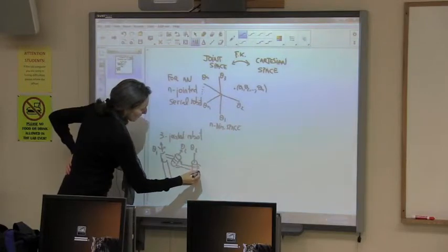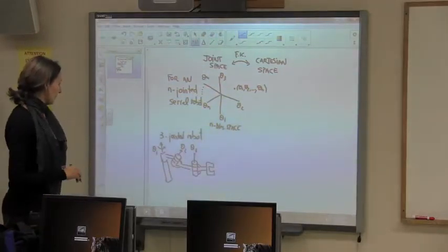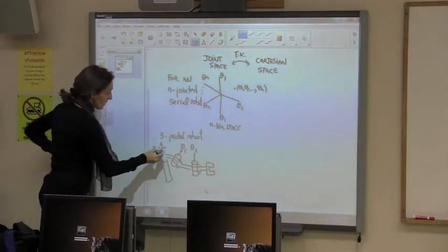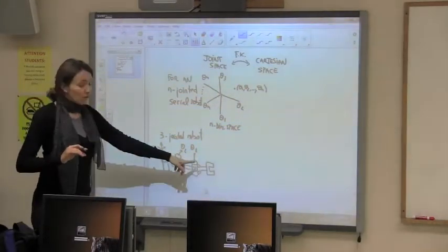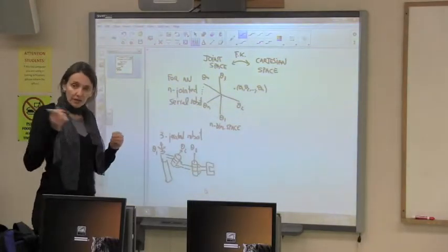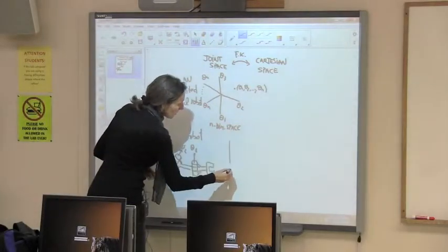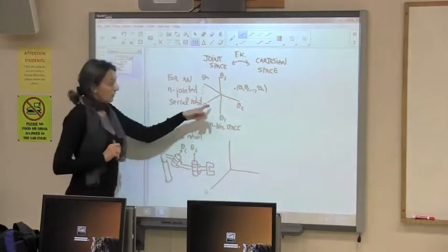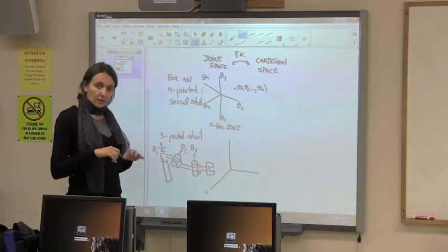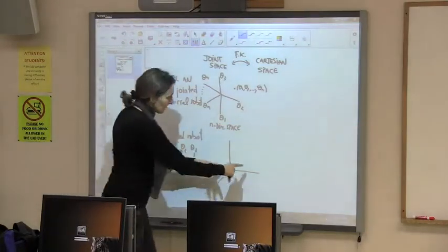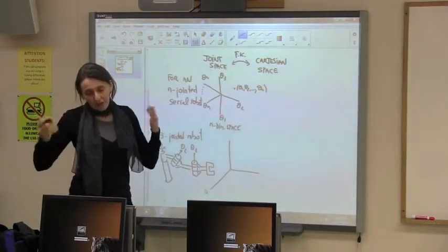So basically in this kind of transformation, everything will be a combination of rotation and translation, right? I'm defining here one with 3 revolute joints, but you could have one of the joints being a prismatic joint, and that will be a translation. Now, from the point of view of the joint space, the angles go from 0 to 2 pi, so those are limited, and the translations go from 0 to infinity. In some of them you will have a certain interval that you will move on. If you have a prismatic joint, in theory you can go to infinity. In real life, this is also limited.